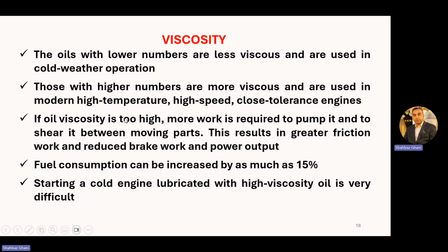So if the viscosity grade is too high, it means it's too thick an oil. So you require high pump work to make it flow between the moving parts. This results in greater friction work and reduced brake work and power output. Fuel consumption can be increased by as much as 15% if you're using high viscosity grade oil. Starting a cold engine lubricated with high viscosity oil is very difficult because the starting motor has to do a lot of work to move that cold engine and the cold oil.